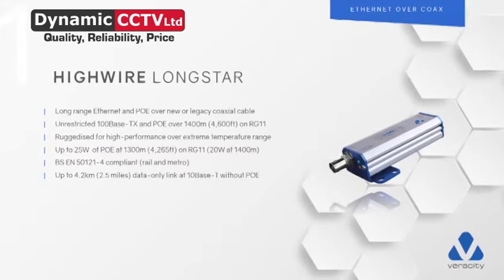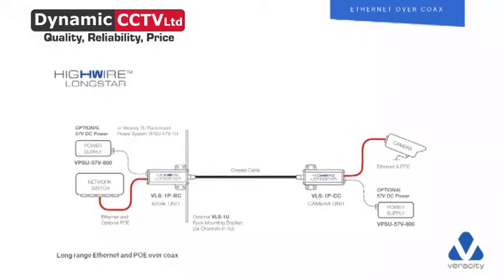That is a vital product. And again, if you've only got 2-3 cameras on, you can use it at longer distances, as you can see off the screen. And off that is 4.2 kilometers on a 10BASE-T network, which not a lot of people look at today. People think that's finished and gone, and it really hasn't. It's still there, it's still a technology, and it still works. So you can utilize it if you need to get greater distances.